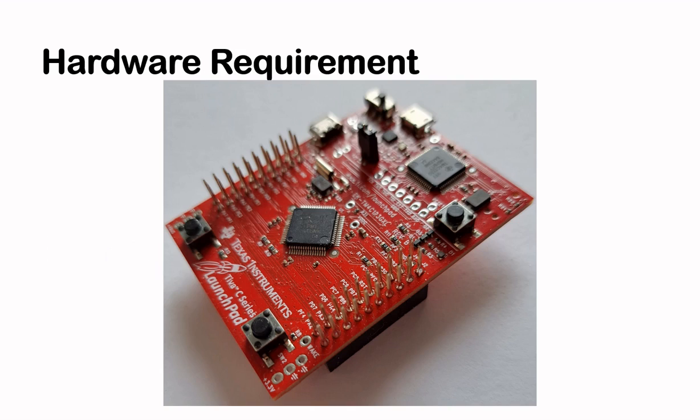Debugging. Hardware requirement. Now, before we can start to debug the program, you need to connect the TM4C123G Launchpad board to your laptop or desktop. Once you've connected the TM4C123G Launchpad board to your laptop or desktop, go to the Keil uVision IDE.